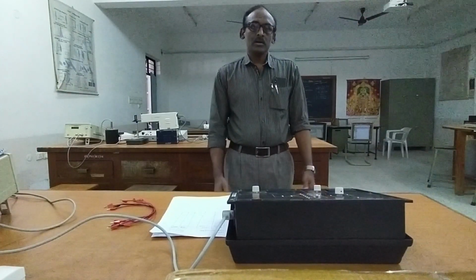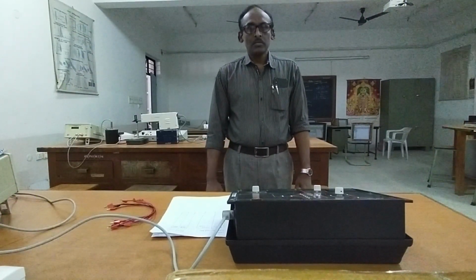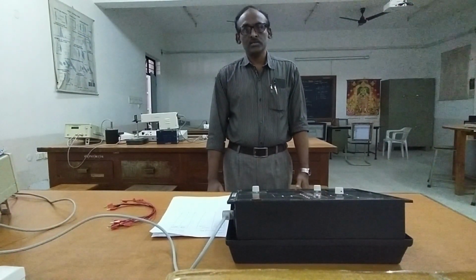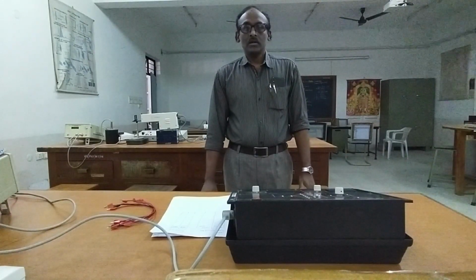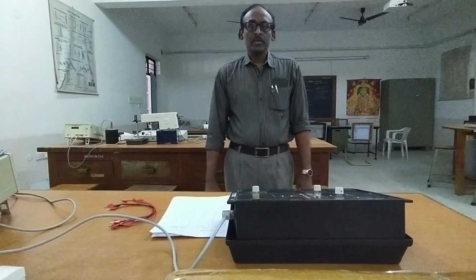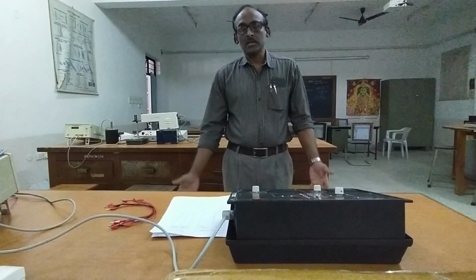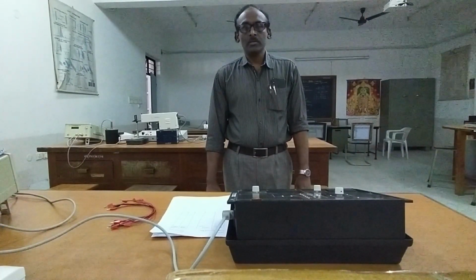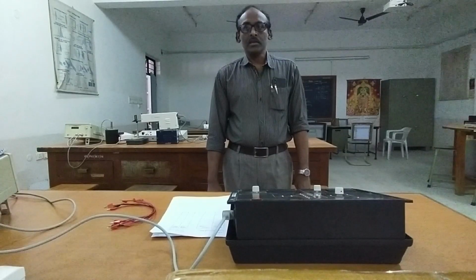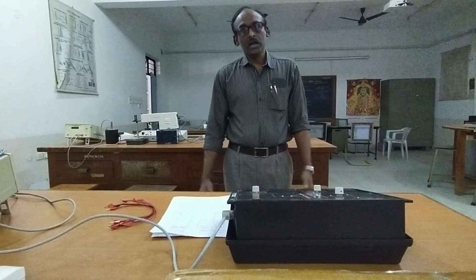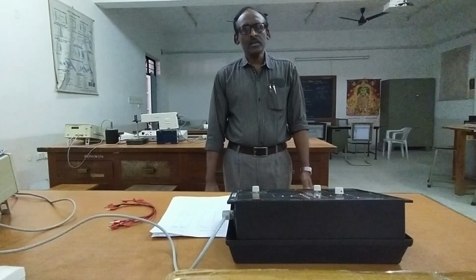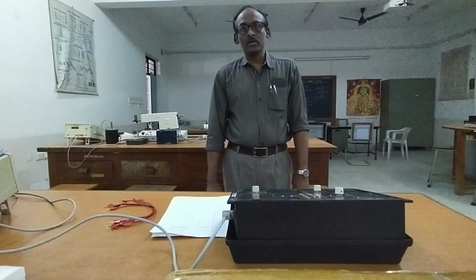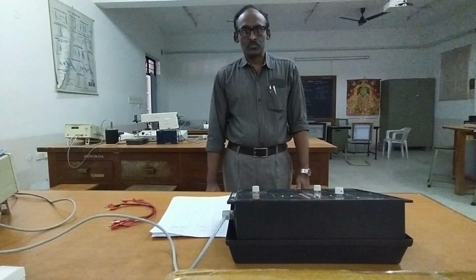So LEDs are cheaper compared to laser sources. Maintenance of laser sources is of difficult nature, whereas LEDs are easy to maintain and also easy to use without much external circuitry. That means lasers sometimes require some cooling system, but an LED does not require any additional circuits or attachments for its operation. LED is very cheap and therefore it is also widely used in optical communication systems as a source.